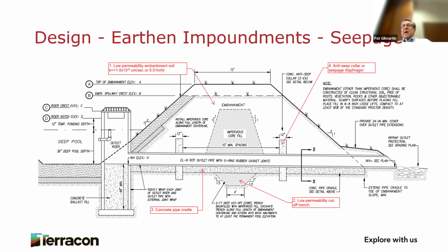Sometimes we see these specified, oh, it's got to be a silt and a clay. Well, these aren't the same as a landfill liner, where we're trying to protect the environment from contamination. We're just trying to keep the wet pond wet or the wetland wet.